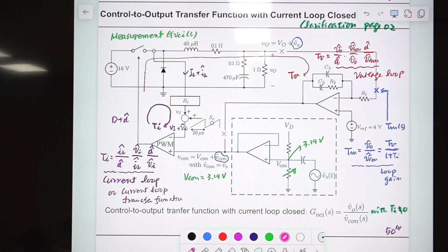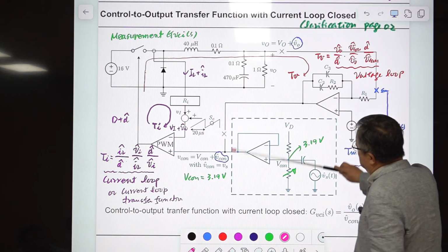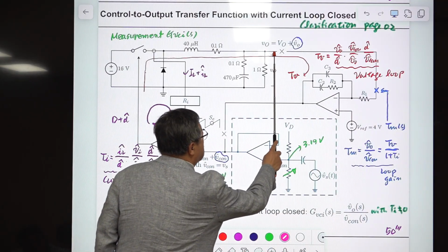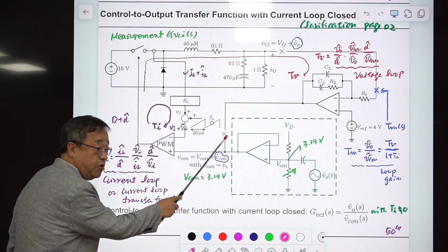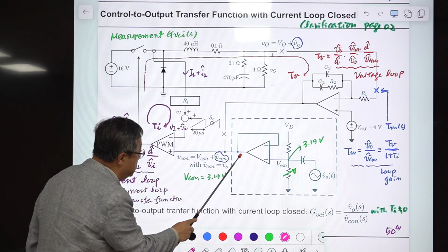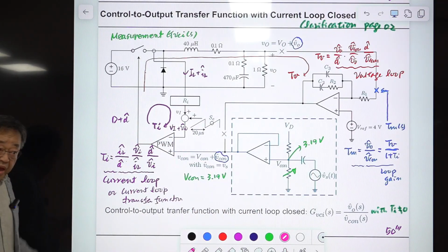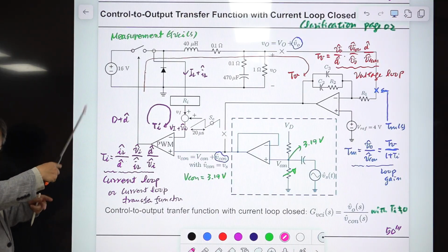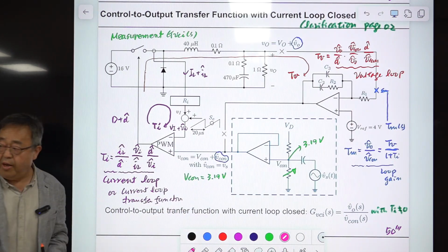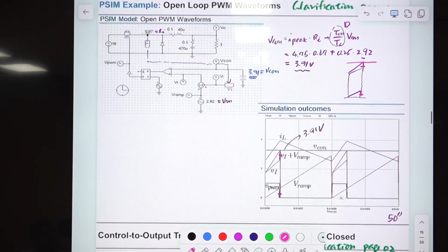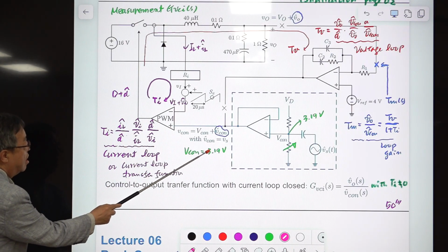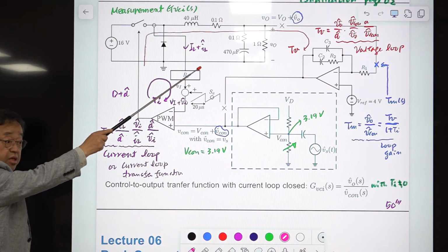All right. So the concept here is, forget about this part. Without this, it is the complete current mode controlled buck converter with connection here to there, and with connection here and there. And you disconnect this, and you insert this circuit to measure this transfer function experimentally or computationally. So you disconnect this, but you have this condition. To generate these waveforms, you should provide this fixed voltage here. So this DC value is 3.95. We previously calculated it in the upper part of this.